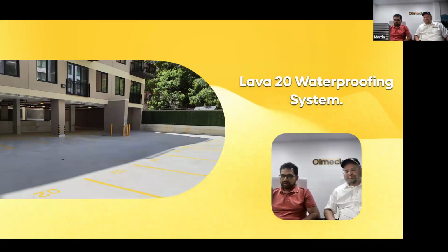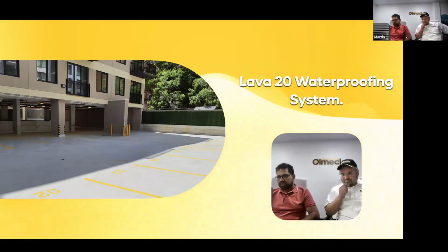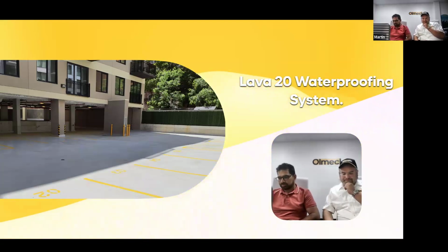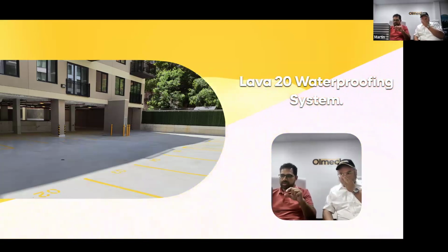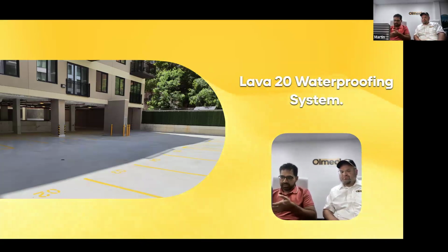And we recommend for high traffic areas, if the parking garage is open and there's no living space on top of it, basically two coats, the first being the epoxy primer. The ratio for the epoxy primer is 3 to 1. And first of all, you would clean the concrete to a certain extent that there's no moisture or anything like that.